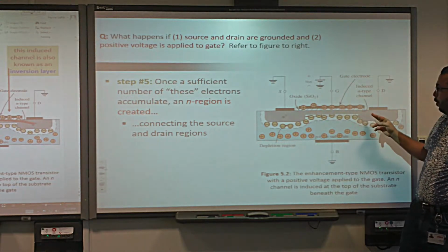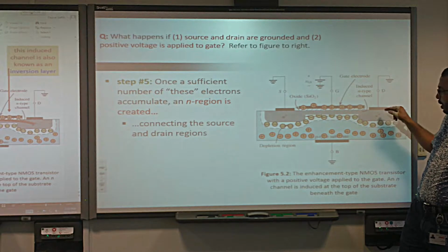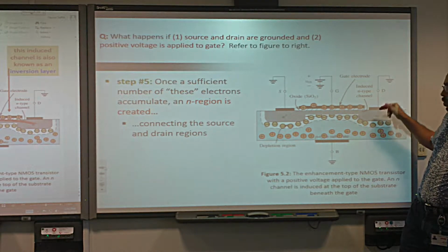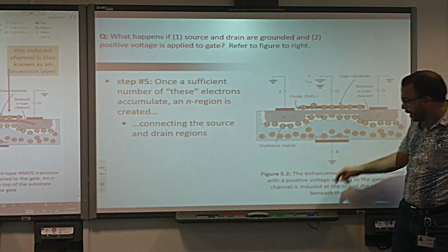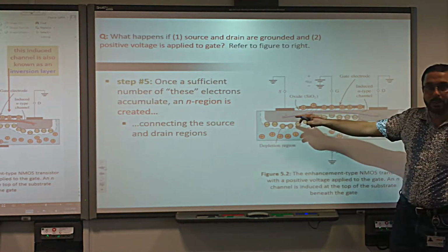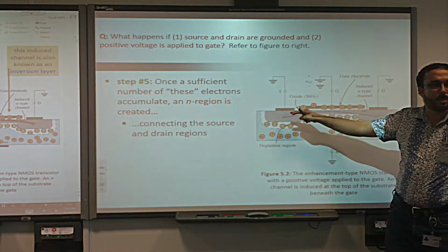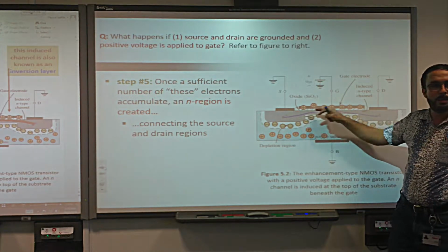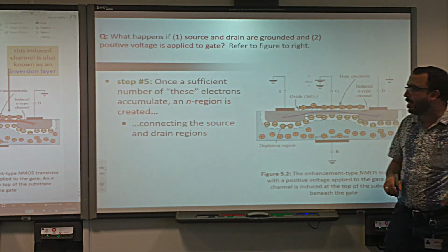That means we basically have a channel between the two terminals here. If we have any current here, if we increase this voltage, we create a current, and that current will pass easily to the other side. Why? Because this channel allows it. There is nothing that stops it. There's no barrier here. Yes or no? See? Now we have created a channel. What does channel mean in Arabic?